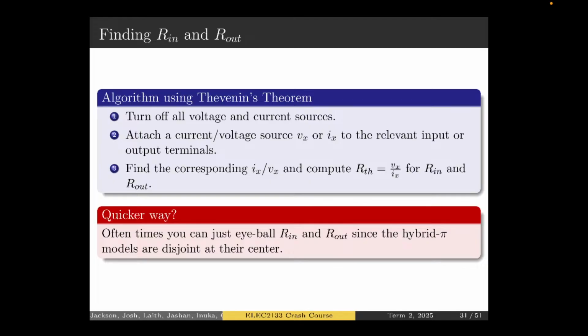Imagine many of your amplifier circuits, maybe a MOSFET amp, with some V out and some V in. If you look from the input, you get some input resistance, and if you look from the output, you get some output resistance. For certain configurations, these would have different values.